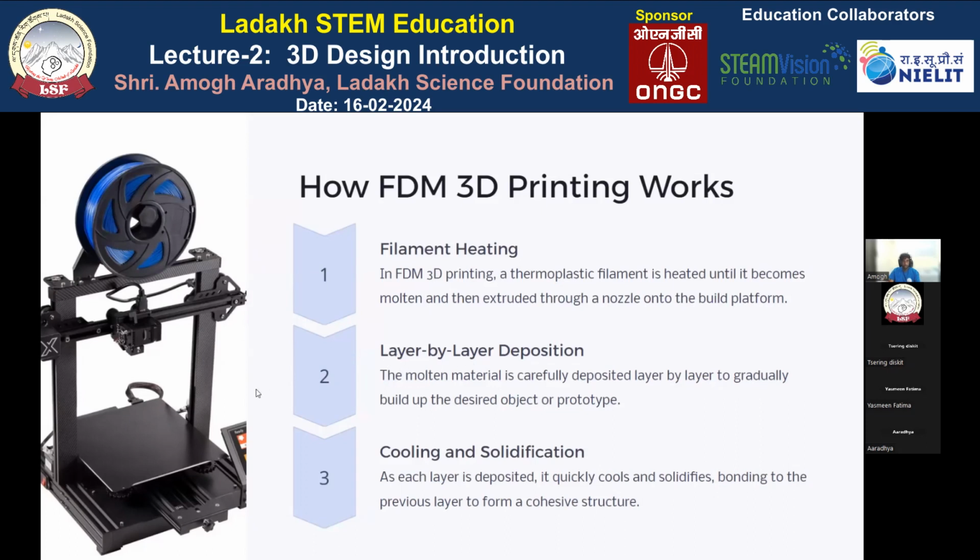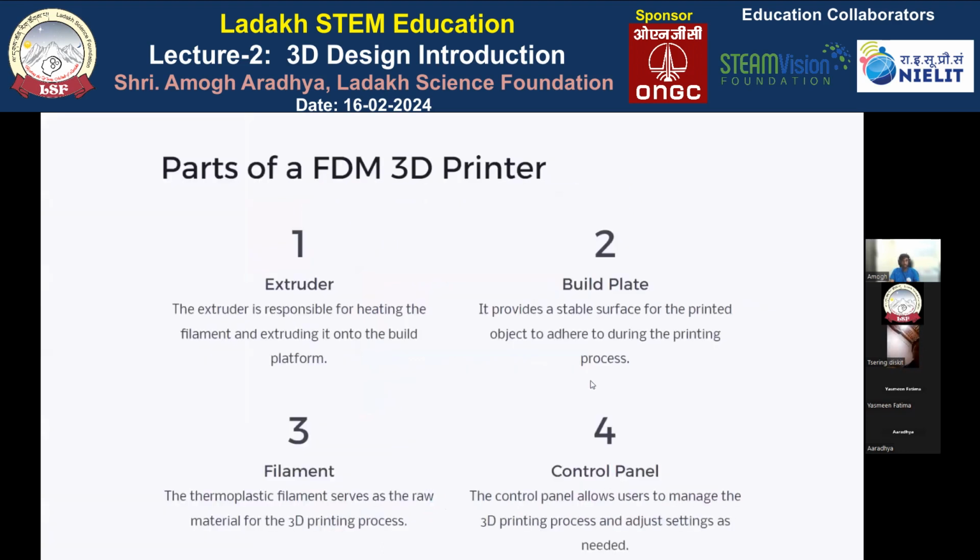So the second step is layer by layer deposition. Once one layer is deposited, the motor will move up, and the next layer will get deposited. So it will gradually build up the desired object loaded into the 3D printer. And cooling happens simultaneously. Once the plastic is cooled, it starts solidifying as the layers are deposited. Because of the cooling, it bonds with the layer, and it becomes a seamless part.